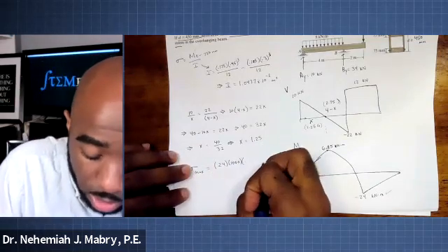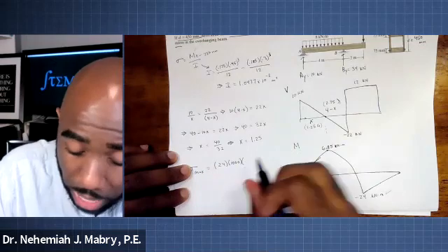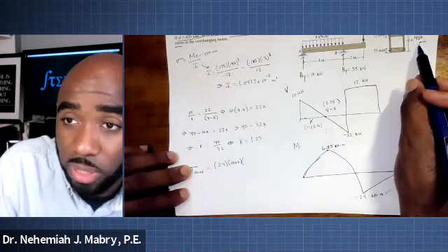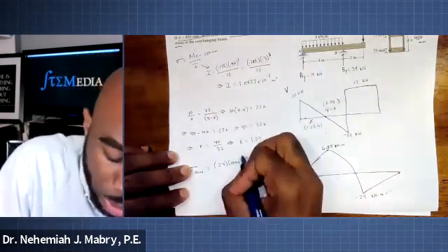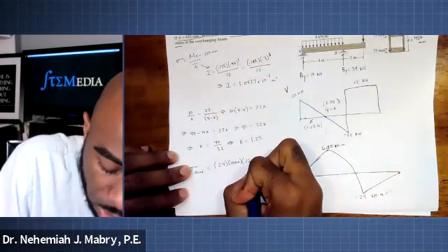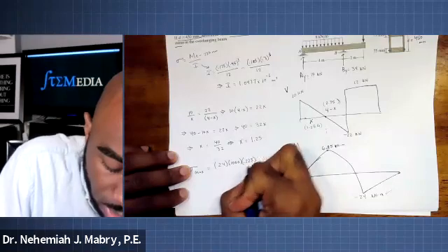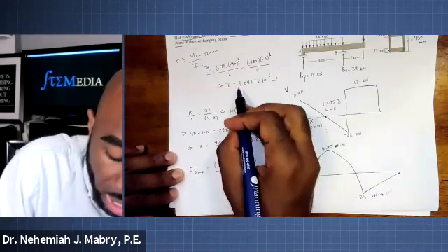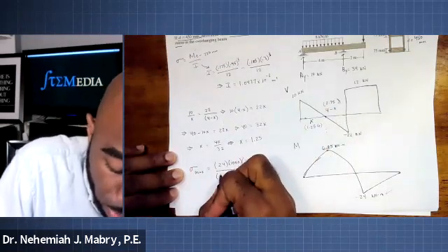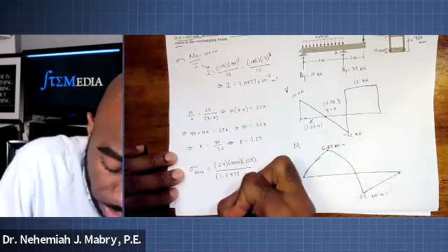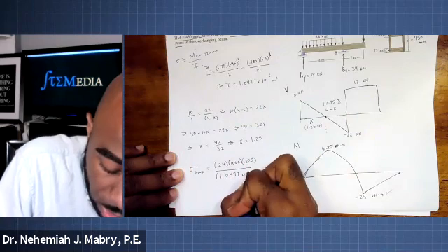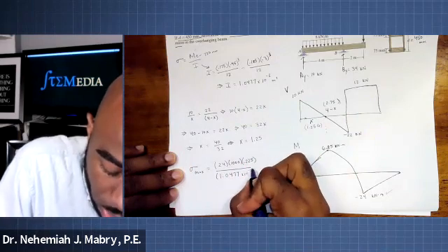And then from there, we'll get C, which we already know to be half of this 450. So 225 millimeters, but we're putting it in meters. So 0.225. Put that all over I, right? Moment of inertia. 1.0477 times 10 to the negative 3 is what we'll go with.